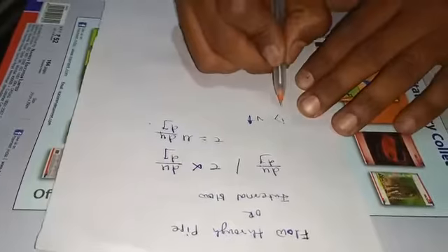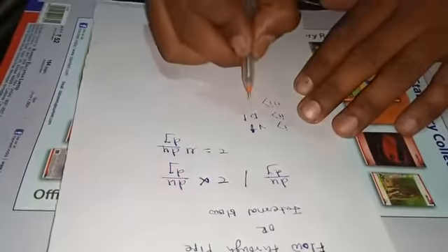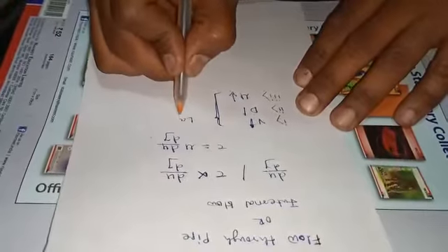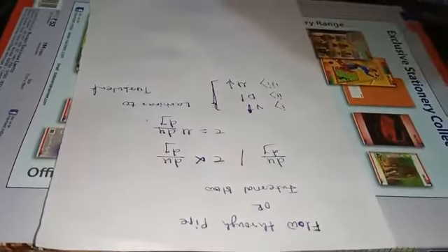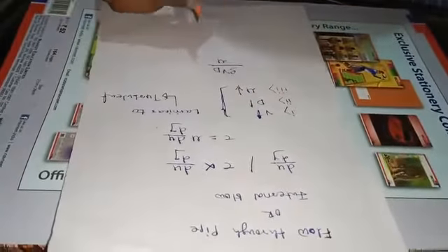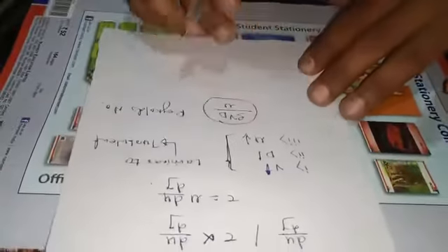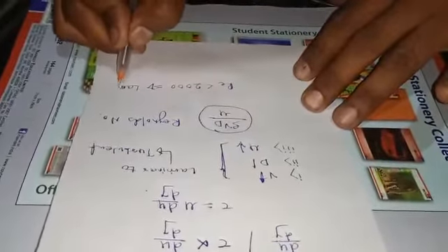So a laminar flow changes to turbulent flow, first, when velocity increases; second, when the diameter of the pipe increases; and third, when the viscosity of the fluid decreases. These three parameters are responsible for the change from laminar to turbulent. But Reynolds was first to demonstrate that not only mean velocity but a quantity rho v d by mu is responsible for the transition from laminar to turbulent, and this dimensionless quantity is known as Reynolds number.